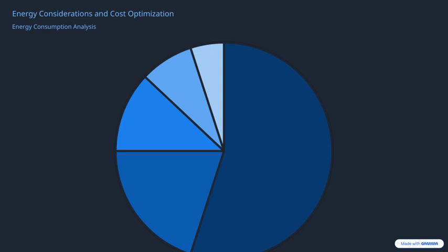Emerging technologies also offer exciting opportunities for energy recovery. Waste heat from blowers can be repurposed, biogas can be used for heating, and solar heating systems can reduce reliance on external energy sources. Energy storage and peak shaving strategies are also gaining traction to manage demand and reduce costs during high-usage periods. In terms of potential savings, advanced control and process optimization can lead to around 25% energy reduction.